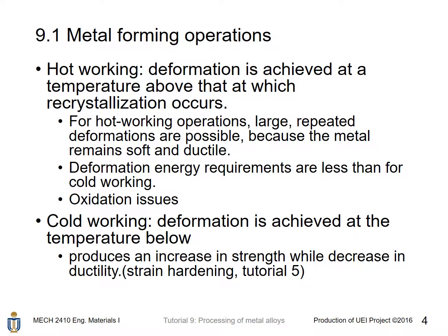For such operations, large and repeated deformations are possible to achieve, because throughout this forming process the metal will remain soft and ductile, and the deformation energy required for hot working is less than for cold working. However, there is a disadvantage. Under such high temperature, the oxidation of that hot worked metal piece will be severe.